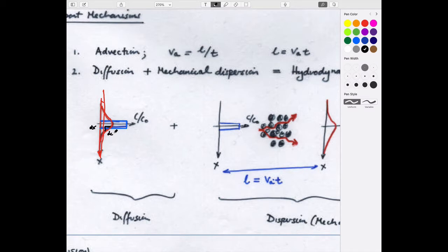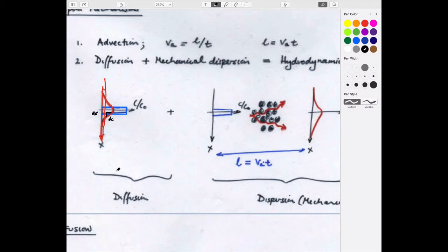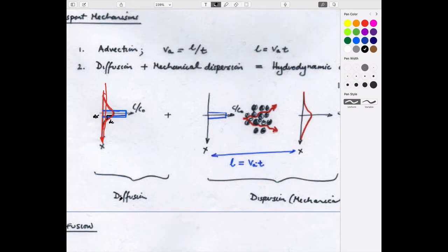And so when you look at transport in the subsurface, we are interested, I guess, in both of these processes. And they operate in different circumstances. Diffusion acts when the physical motion of the flow is so slow that the only spreading mechanism is by molecular diffusion, Brownian motion. And dispersion, conversely, operates when the flow velocities are large, the mixing in terms of going up and down different pore routes is varied, and therefore the mechanical mixing completely dominates over diffusion.